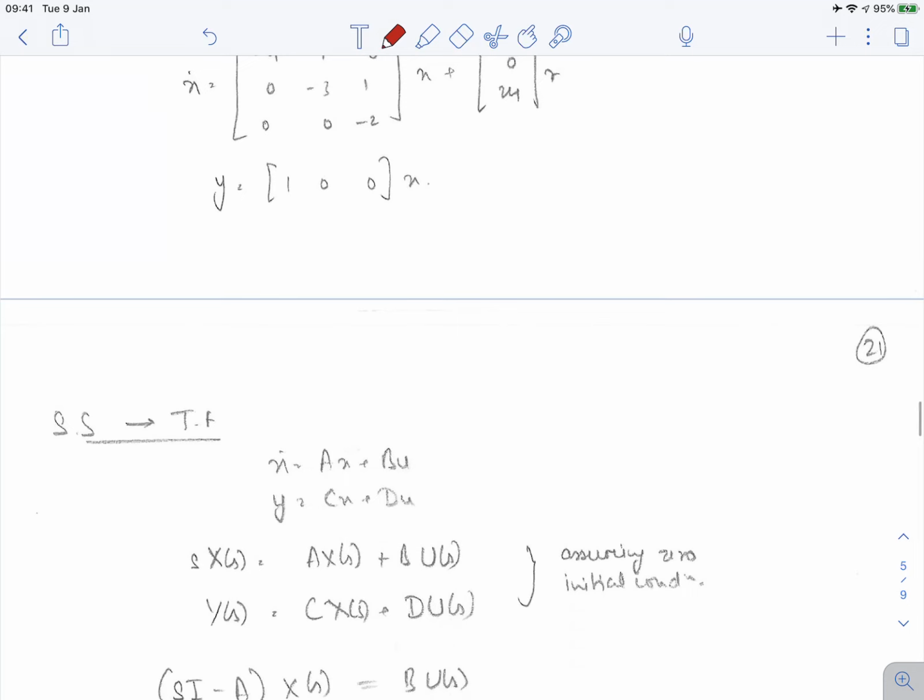So first of all, what I would suggest for this tutorial problem, if you have it open in front of you, is to first write the complete transfer function Y(s) over U(s). Because this is a feedback configuration, and in the forward path you have a third order transfer function, because of the multiplication of the first order and the double integrator. So once you have obtained this transfer function,